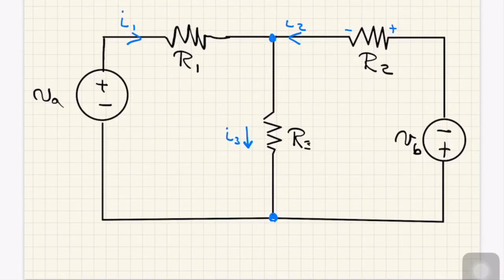So let's see what that means. All right, so let's start with the diagram we had before. We had the various currents and signs on it. Let me finish up with those signs. So now we have the plus and minus signs all laid out. So that's the circuit we started with. Now the idea here is to simplify the circuit, and we're always trying to get rid of a branch. Ultimately, this is the goal that we set ourselves. And obviously, getting rid of the branch that includes I3, which was our solution, is maybe not such a smart idea. But we could get rid of this whole branch on the right-hand side if we set the value for R2 to be very large. Because if that becomes large, as in toward infinite, then that whole branch goes away.